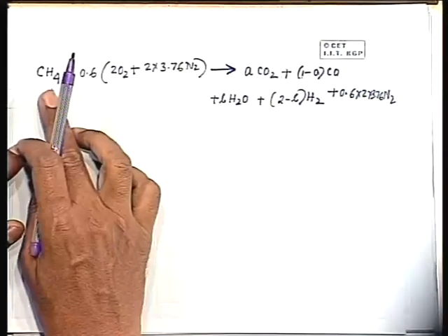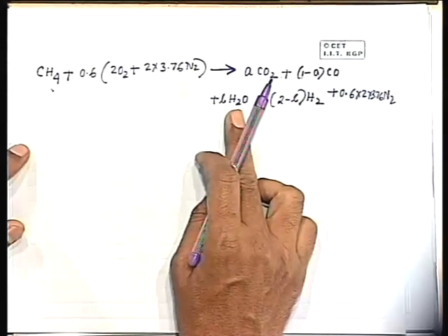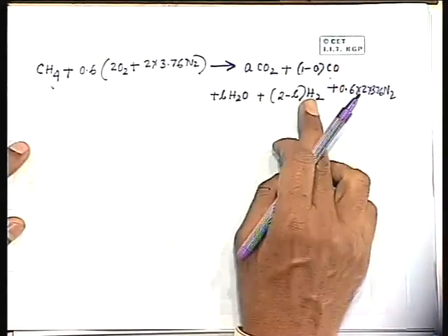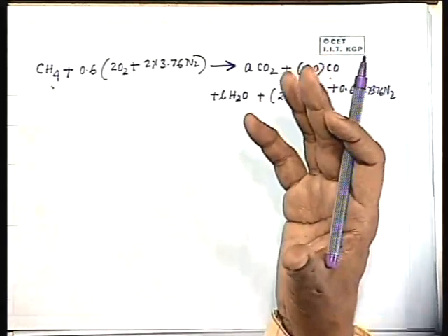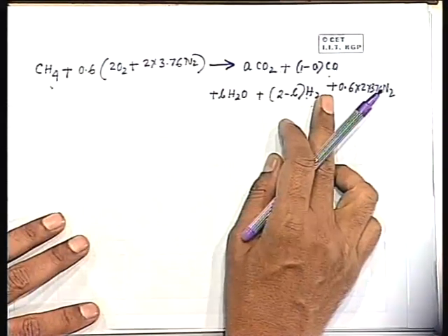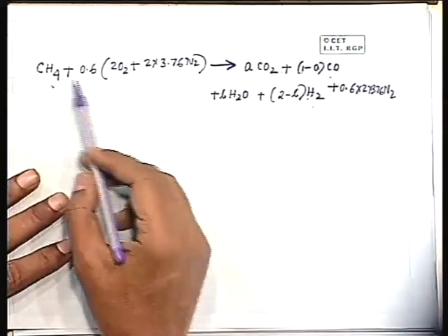If all the CH4 was converted to CO2 and H2O, then I could have told you this is complete combustion. Now when there is CO and H2, from the enthalpy point of view, this can again burn with oxygen and give water vapor and carbon dioxide, which could liberate more enthalpy. In a very loose term, more heat will be generated, though it is not a correct term from the thermodynamics point of view. That means the temperature will increase more. That means there are some burning elements remaining. That is the reason this type of combustion reaction is called incomplete. Still we can exploit enthalpy from this.